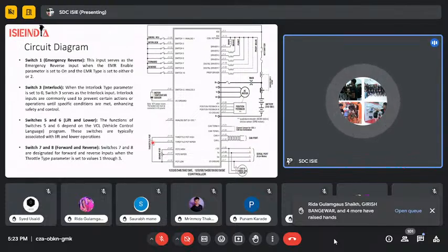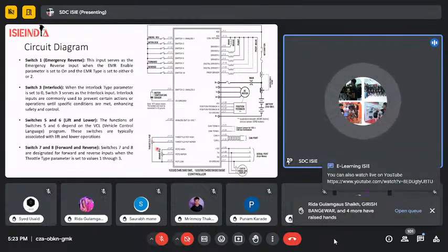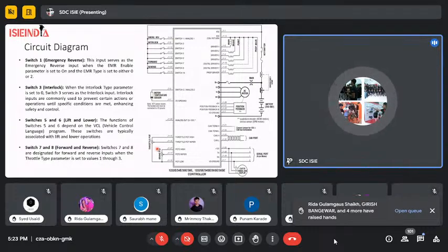In the majority of cases we have used electric throttles. In the electric throttles we have a bipolar linear Hall effect sensor. Okay, linear Hall effect sensors are there, and with the help of magnetic variation, strong magnetic field and low magnetic field, we can give a variation in the voltage, and we can operate the motor very quickly.